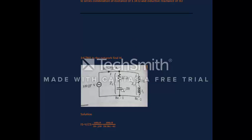From this we can easily see this is the Z1, this is 10, and the current flowing through is 10∠-10° ampere, and the voltage supply is 100 volts, which does not have any angle, and the total impedance is Z2. This is the resistor of 10 ohms and this is the inductor of XL, which we have to find out.